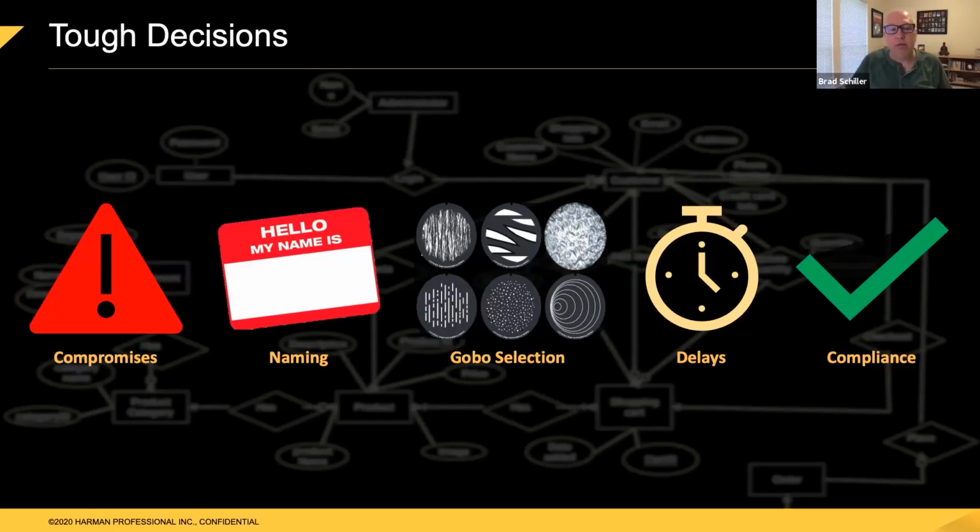You send this unit off, and they'll test it electrically, and the FCC will test for emissions of different radiation and different frequencies. They might also test for pinch points of fingers, all kinds of things that hopefully you caught, but if you didn't, they're going to send it back to you and you need to make corrections. Those corrections take new engineering time, maybe new tooling, and then once you make those corrections, you've got to send it back to the lab, get back on their time frame, and get that compliance approved again. That is all delays that can happen, and you've got to make decisions around that and decide how you're going to ultimately get that compliance.